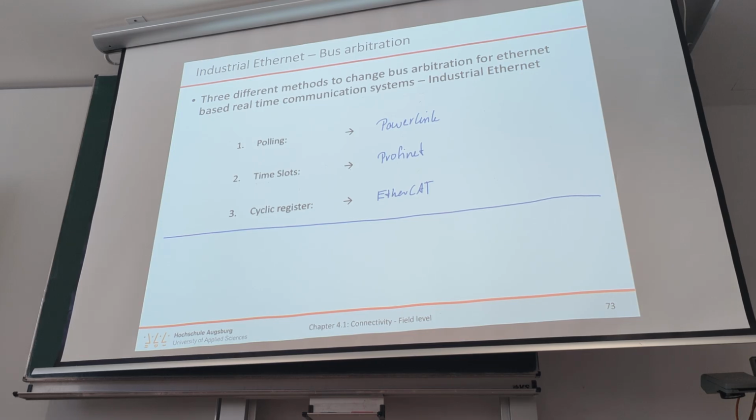And you send that to the ring, and the slave just takes out the data it needs and puts back its output data, so that finally at the end the output data arrives at the EtherCAT master. And that also works with very high performance and is, in terms of organization, much simpler than the time slot approach.